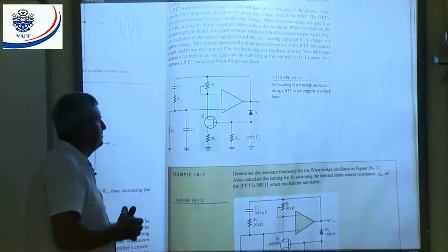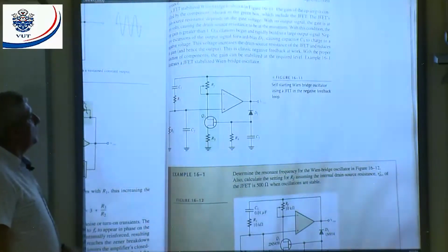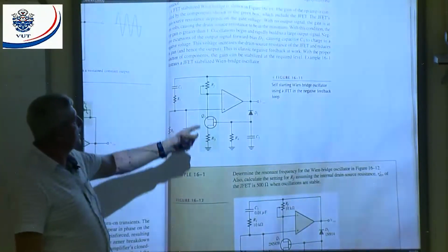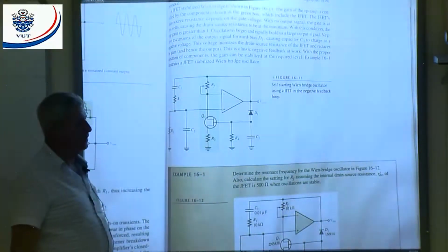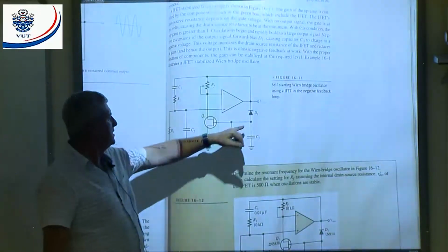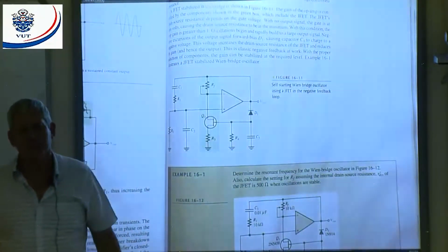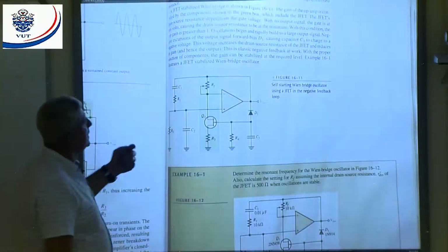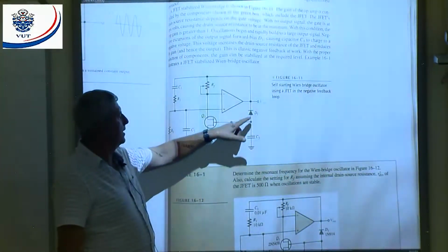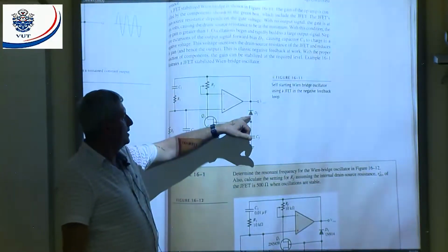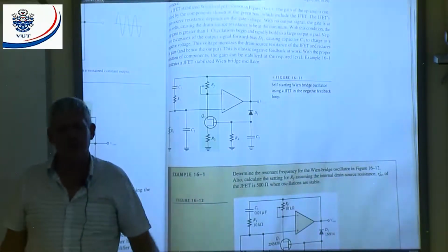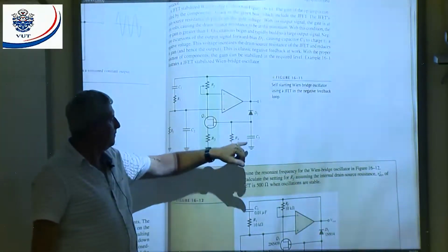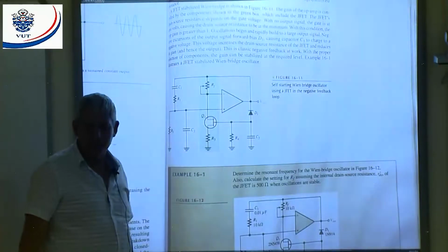Now what happens here? If I switch on, this thing will automatically control the gain. When I switch on, the voltage here will be basically 0. When it's 0, there will be a current flow. And when the output starts increasing and then decreases, creating a negative cycle, this diode will be forward biased during my negative cycle. That means it will charge this capacitor negative, positive. All right. You with me?